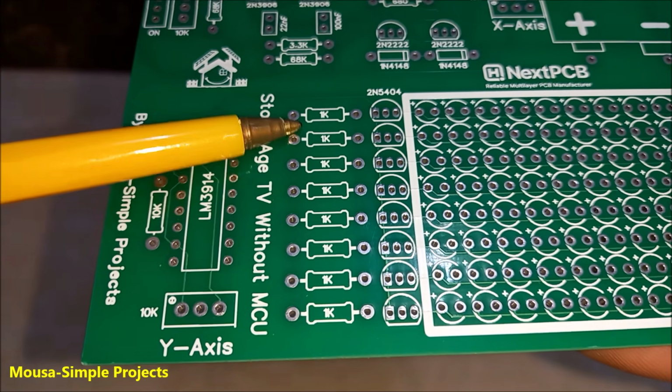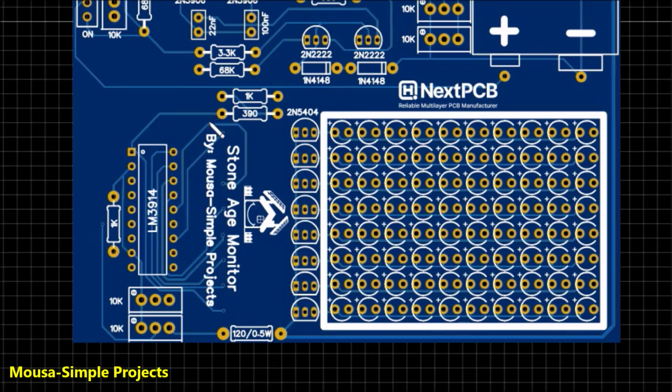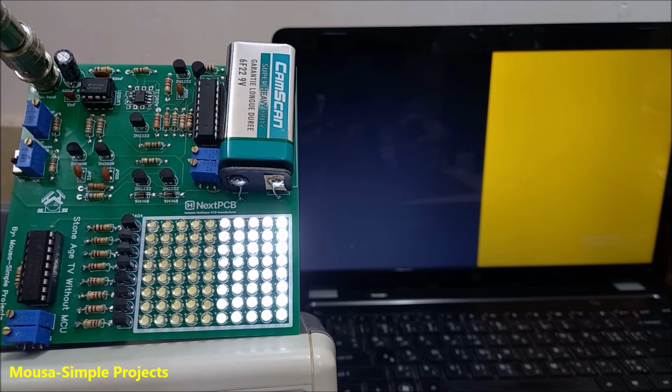I was using resistors on the base of the transistors, but they are not necessary, so I removed them because the IC has constant current drive. The color of the image doesn't matter. The LED stays on as long as the color is not black.